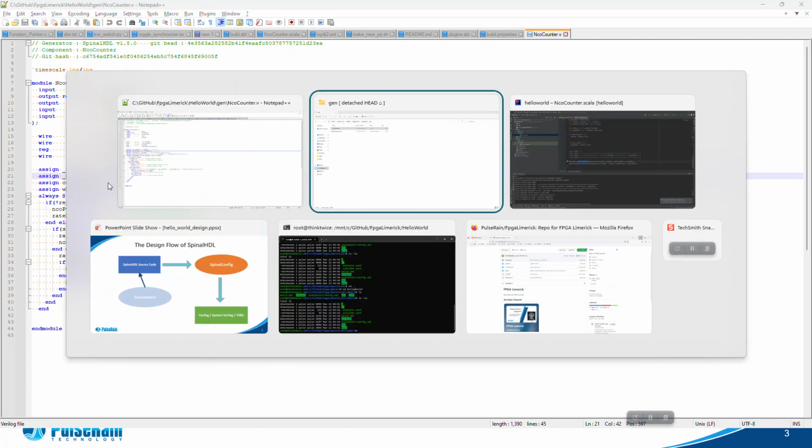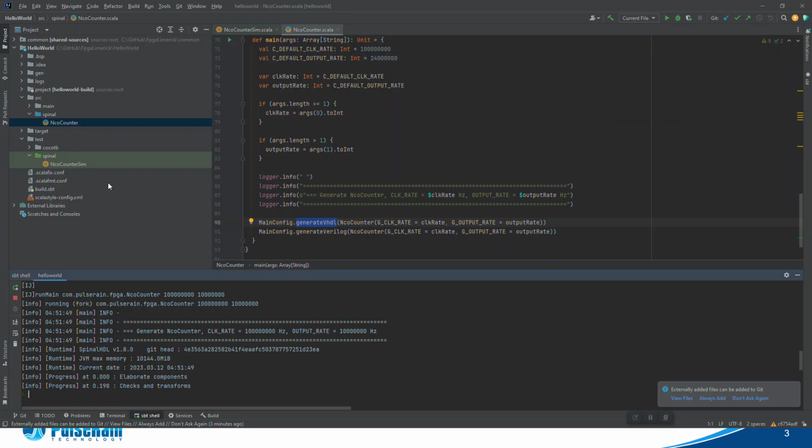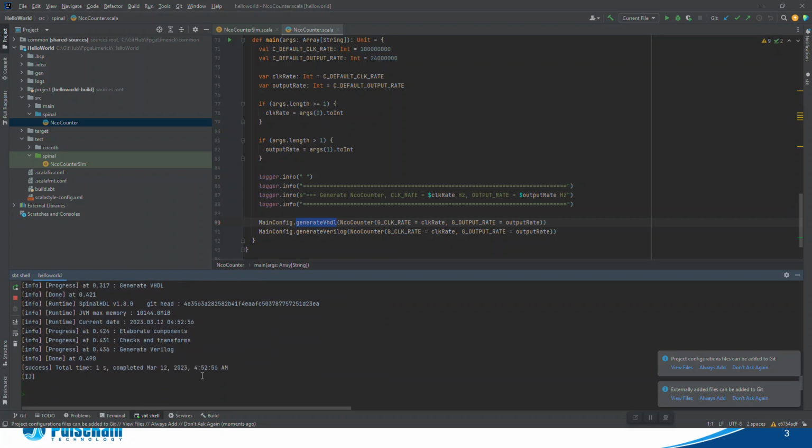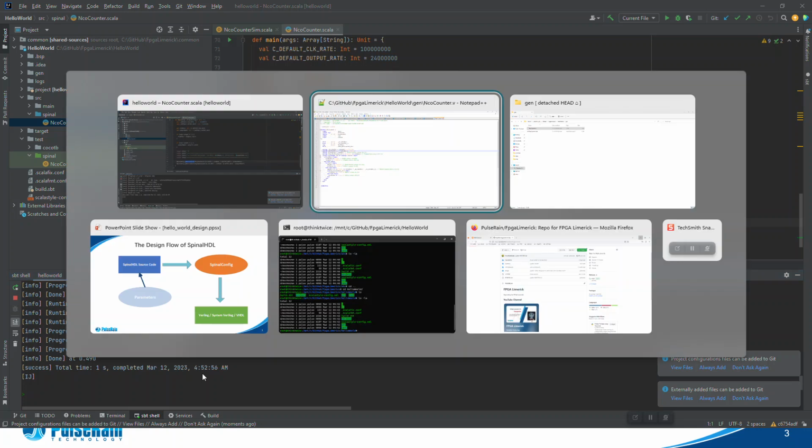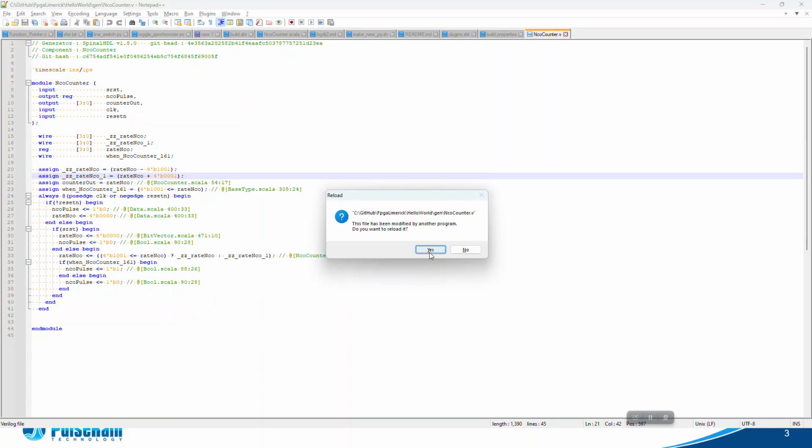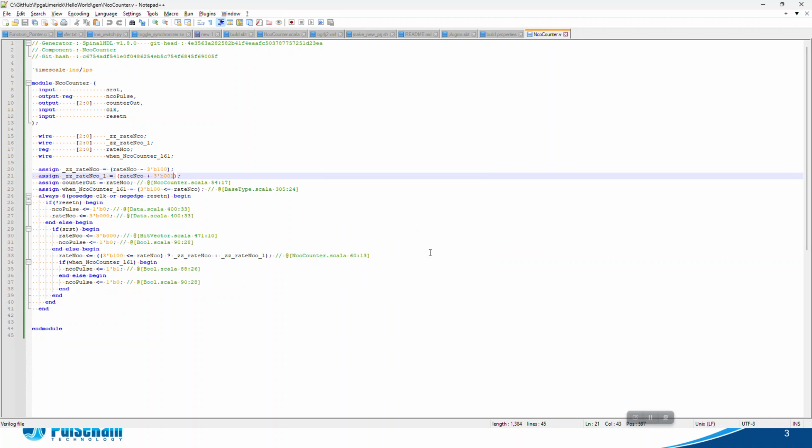Now if we do that differently, we say instead of 10 we do 20 mega. Okay, now the Verilog file generated has also been altered. It becomes adding 4 and 1 for the counter, and the counter value we will explain soon.